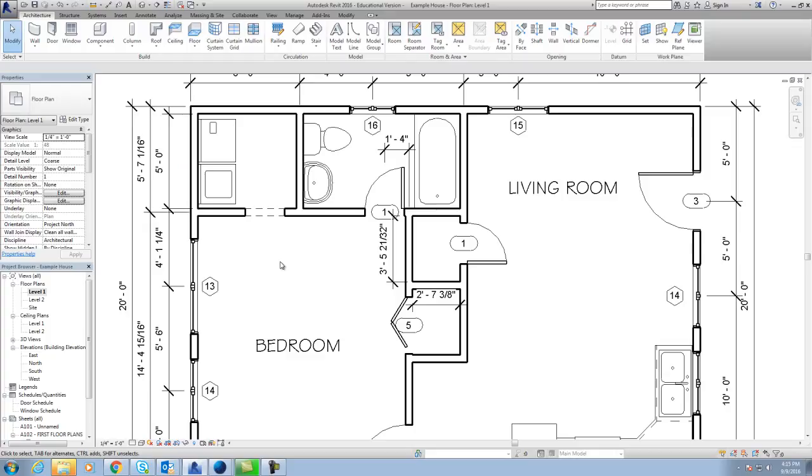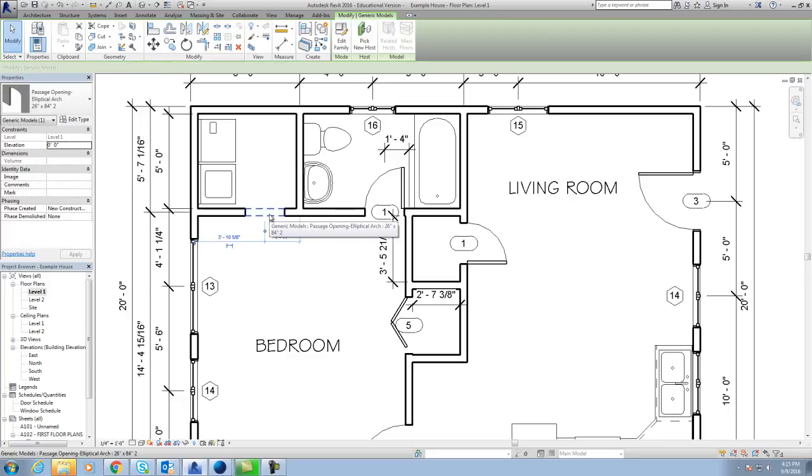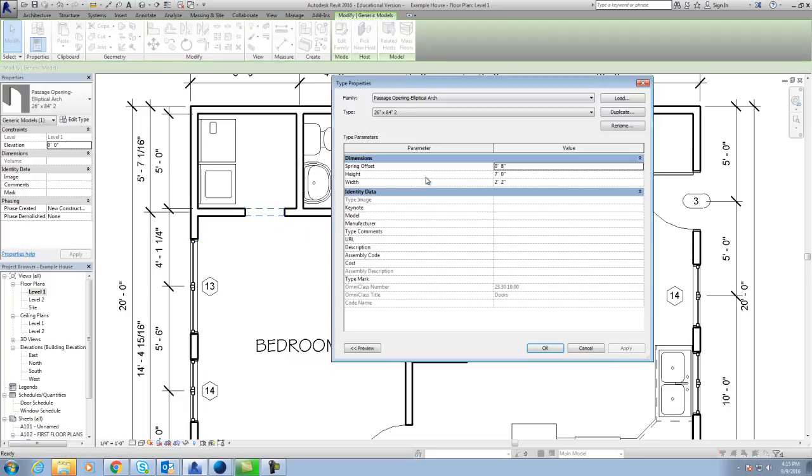Another thing I'm really concerned about is when I hit annotate on this washer and dryer here is to make sure there's 2'1". I got to make sure that this thing will fit through these doors. You got a 1/2 inch clearance on both sides of that. So it's really tight. I would open that door up a little bit on my opening edit, and that is a 2'2" width. I'd open that up to at least 2'6".